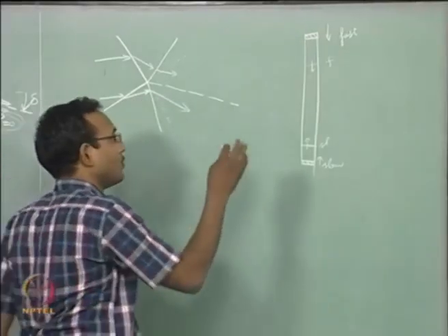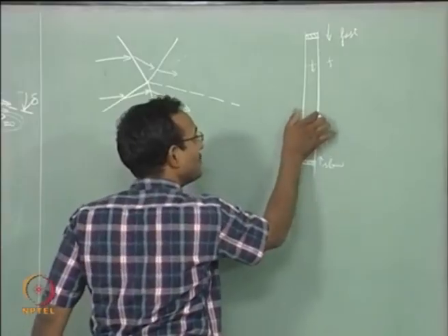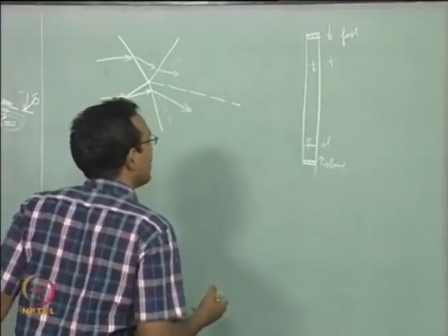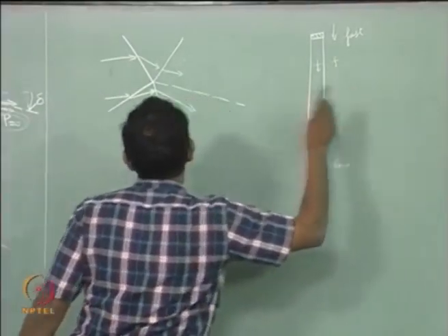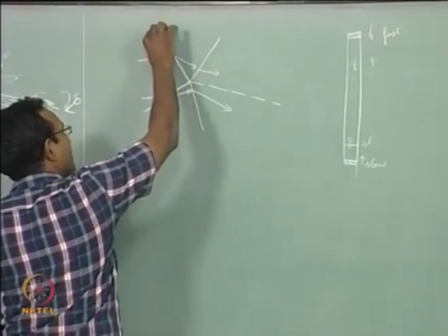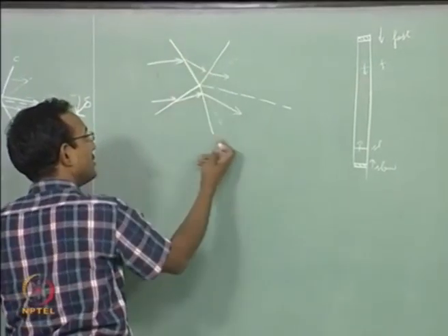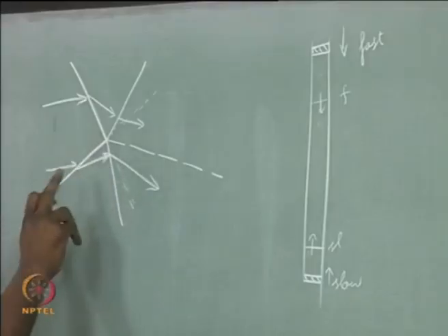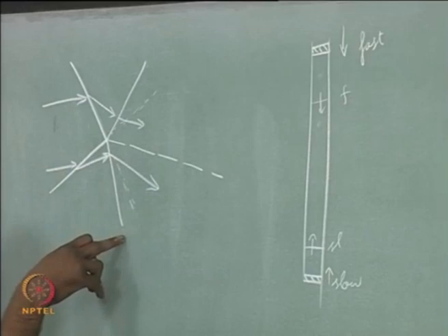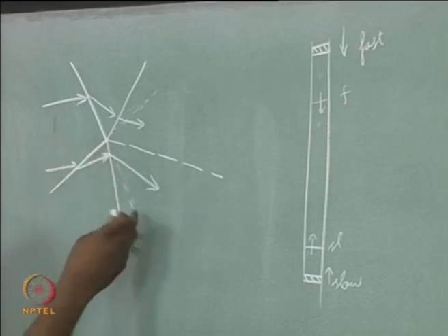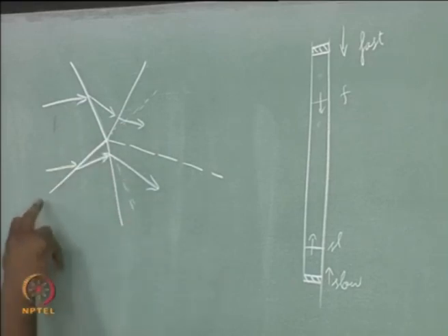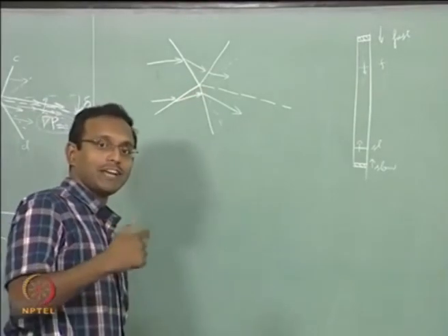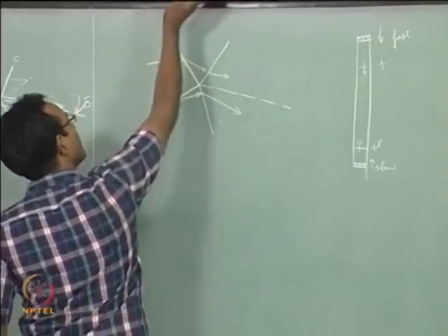Now imagine this whole thing happening here while I move this cylinder this way. That becomes our piston analogy from 2D to 1D, right? So as this is moving, I will go to this particular case where the stronger shock gets to go past this weaker shock heated gas, which means it will not be very strong after the shock interaction. So it will just go a little forward. While the other one, the weak shock, is going to go after this point into a strong shock heated gas. So it will deflect more that way.